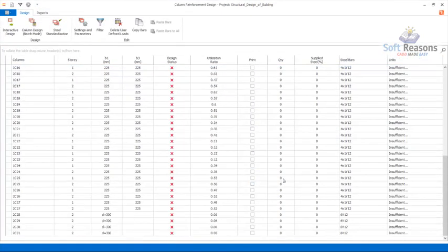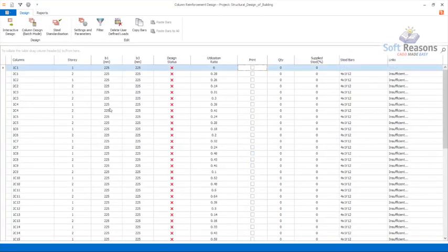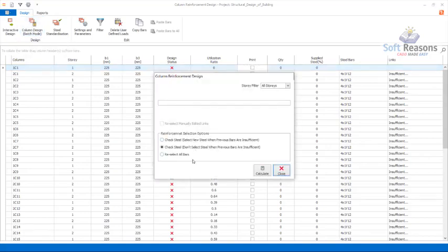I have to get this expanded, and then you have all of this just like this. Come over to the column design batch mode. Select that option. So this is the option that the default design was used. So select these other options, reselect all bars and click on calculate.